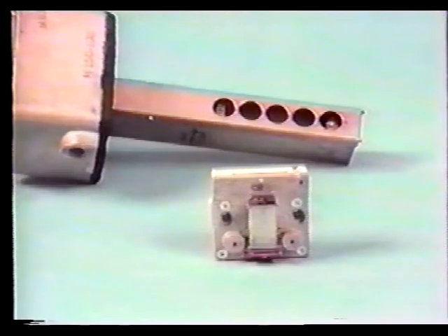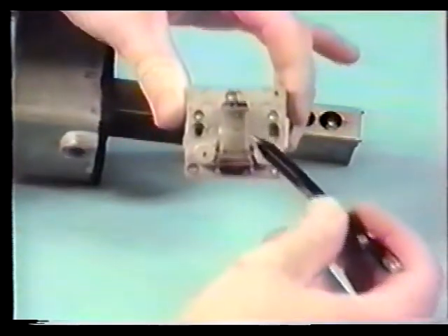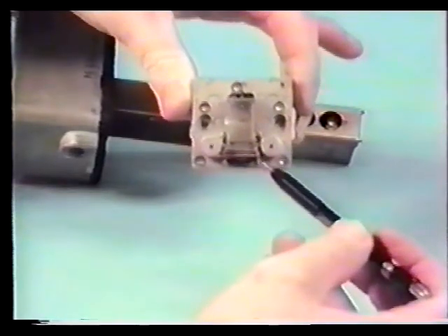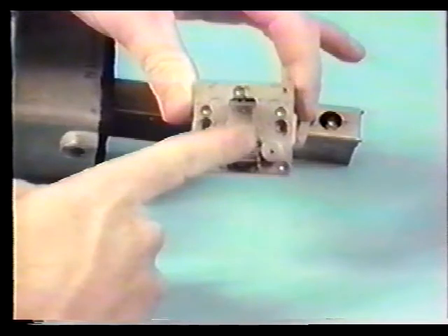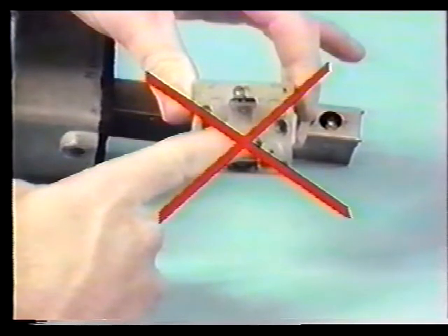There are two types of humidity transmitters: the room transmitter, which is wall-mounted like the room temperature transmitter, and the duct-mounted humidity transmitter, which is used to sense the relative humidity in an air duct. The humidity transmitter uses a very sensitive hygroscopic element to sense the relative humidity in the air. One must be very careful not to touch this element, as the oils and acids from the skin will deteriorate the accuracy of the device and render it useless.